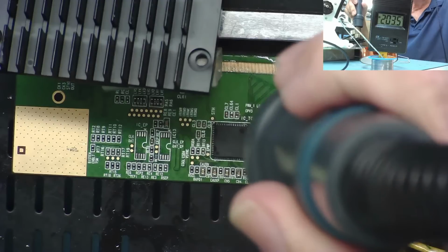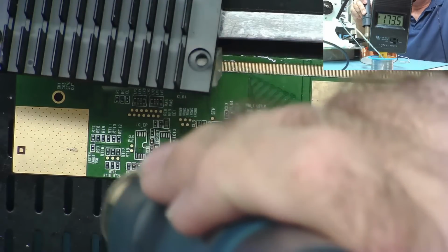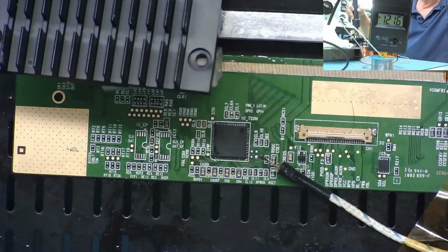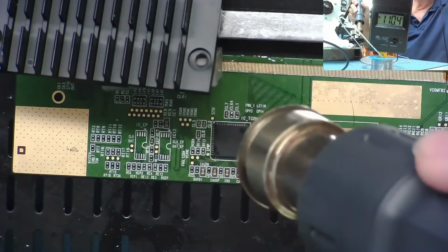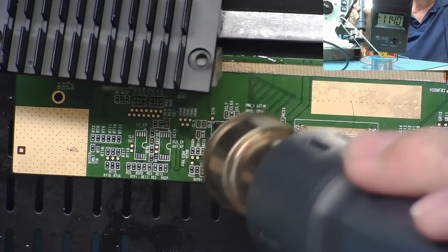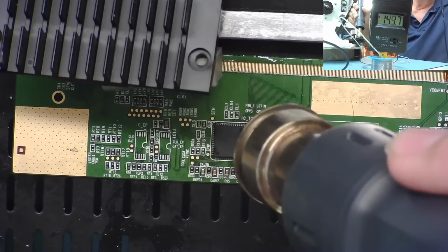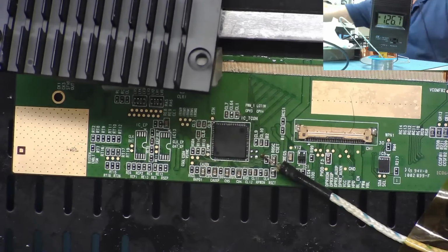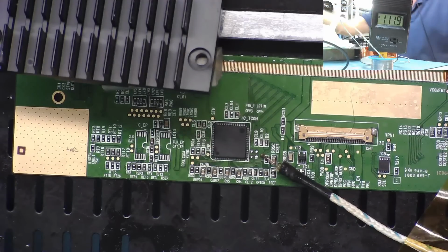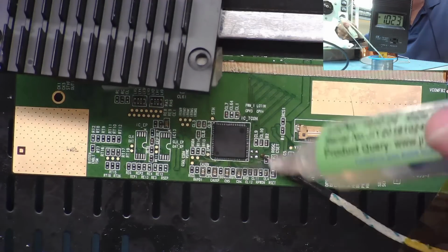It's hard to do like this because you've got the hot air blowing on, you can't really see. I've just taken it away. So really it's less than 100. I think probably more visibly I'm going to have to go by what happens with the chip. You see the flux. There is flux under it, but let's add a bit more flux around it.